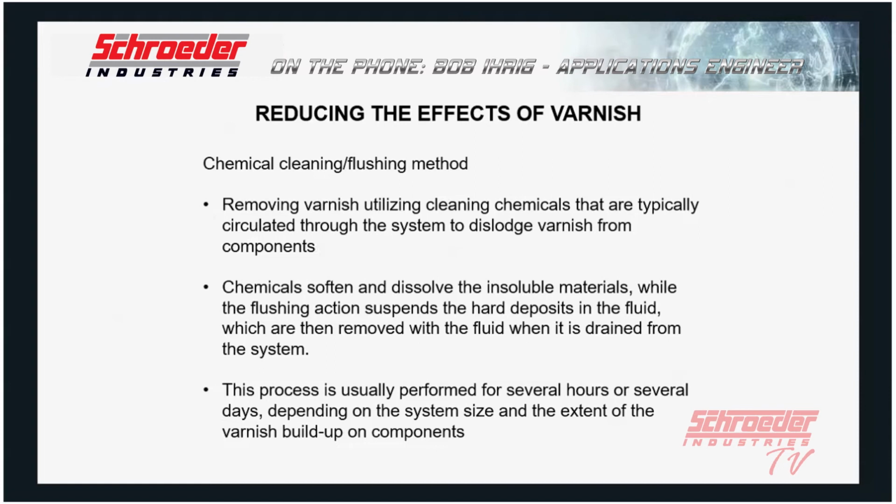Obviously, the concentration is proportional to the amount of fluid and the fluid type, etc. Then that fluid is cycled and ultimately disposed of once the varnish that has deposited on the system components has been dissolved into the fluid. Then new oil is added to the system, cycled, then discarded as well.